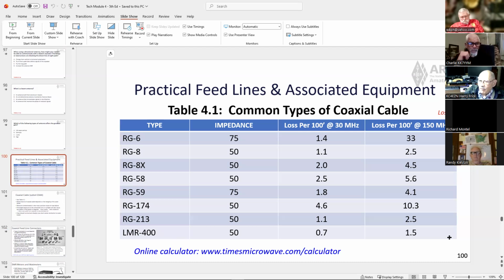And one night I turned the radio on and I don't know what went wrong, but the tuner went crazy. SWR went out the roof, and I went out the next day and took the antenna down to check my connections. As I was running my hand down that one section of the antenna made out of the RG316, I discovered that I had evaporated not only the jacket, but the braid on that RG316. Now that was some Chinese made RG316. Again, when you're looking at where to spend your money, don't buy cheap coax.